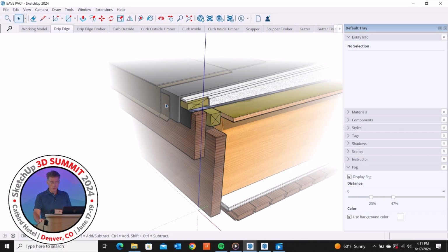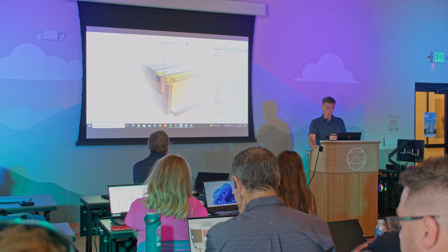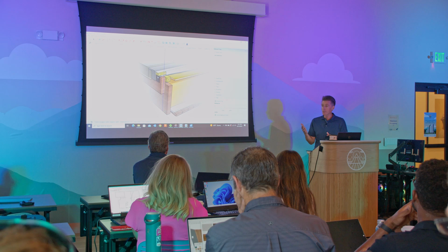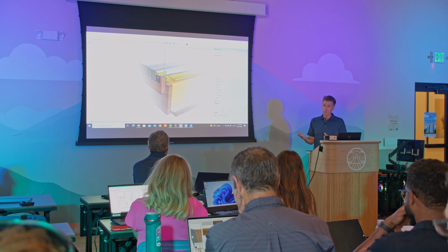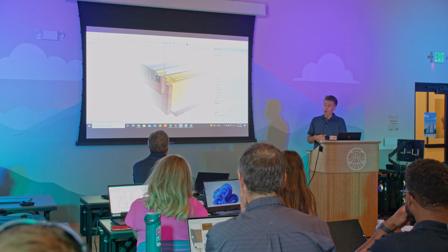In this case, it's showing a cleat tying to a flashing piece that then goes underneath the flashing cap of the PVC, and then the PVC roofing rolls over the edge, so it kind of double protects it in case the seam at the PVC flash fails, which I've never seen that happen. But just in case it does, water would still not get into the assembly.